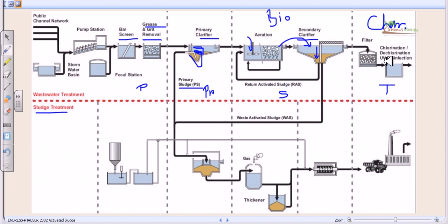We can do this by utilizing UV disinfection, or we can do this with the help of another chemical treatment by utilizing SO2. Sulfur dioxide is a very important key player in this case. So we add sulfur dioxide, or use UV disinfection, and then our water is totally pure and ready to be discharged into the stream again.